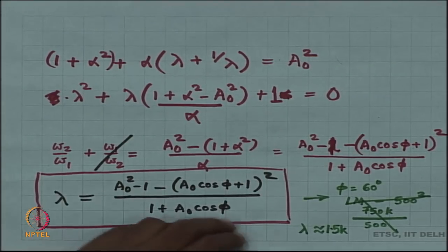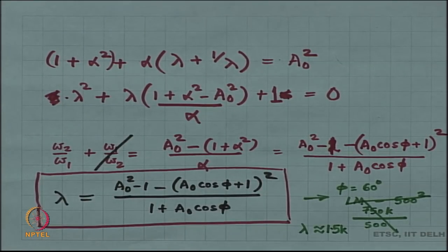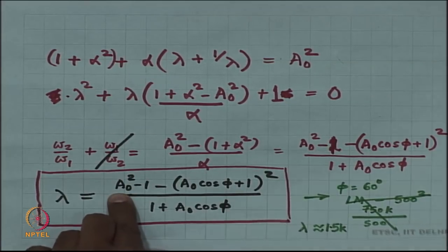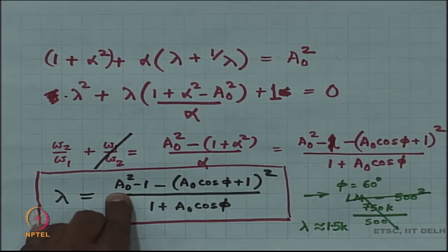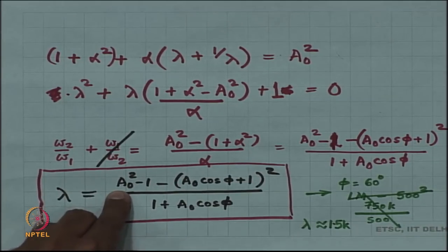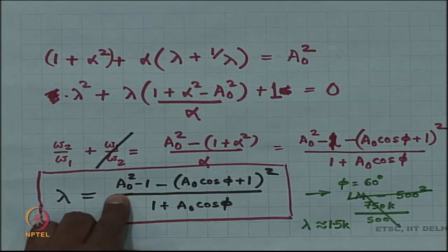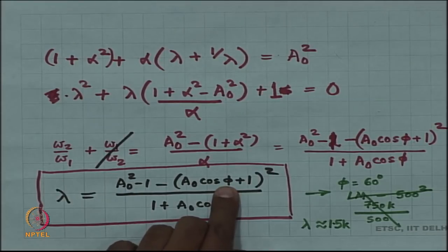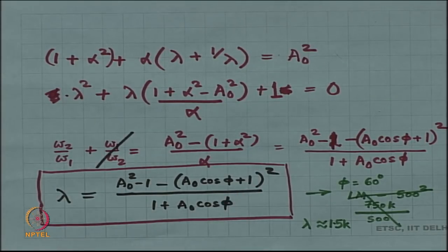Okay. Now, when you have designed this plain vanilla amplifier, you already know the value of A naught, that is fixed. We do not want to tamper with it, okay. We do not want to touch it. The boss comes into your room and says that before you sign off on the design, make sure that your phase margin is 60 degrees or something. Okay.